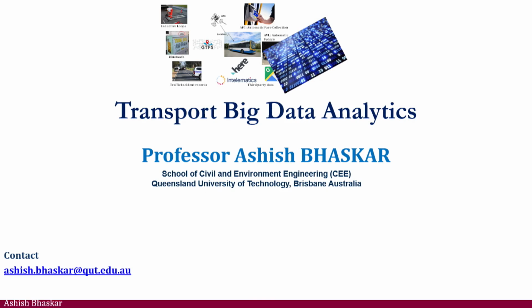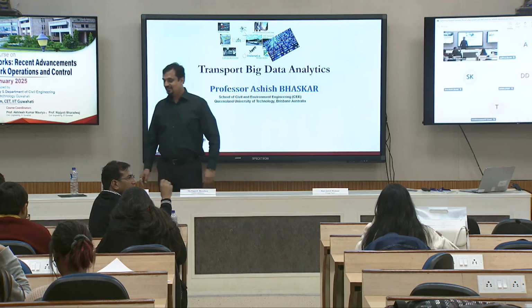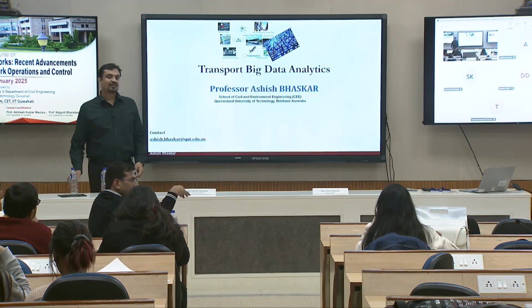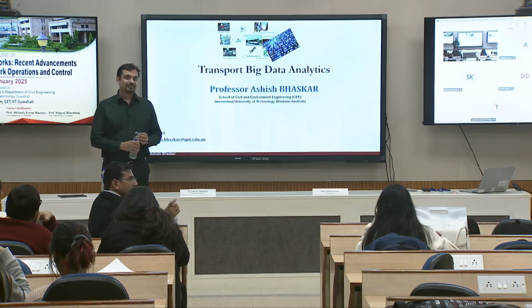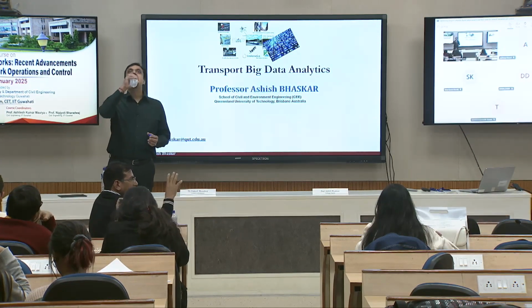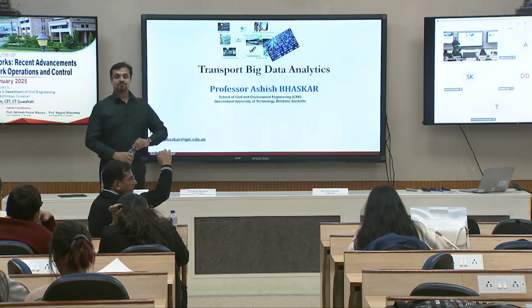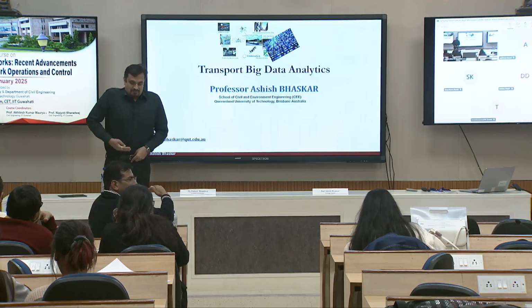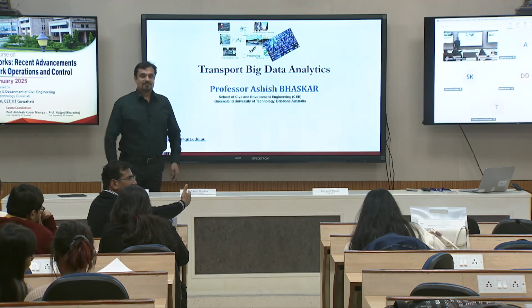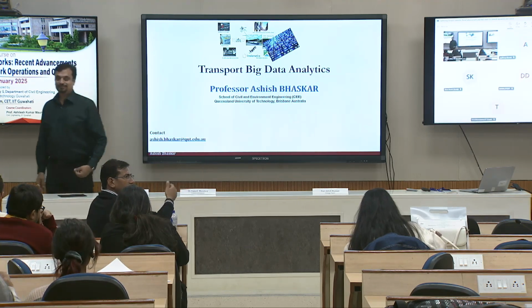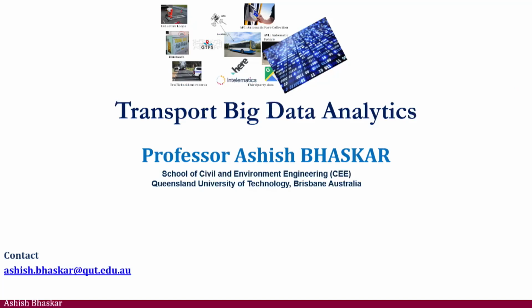You can connect it with whatever he has discussed about the signal, where you are blocking for some time and opening for some time. For the time you are stopping and then activating, you are losing something. So basically, you can assume that that is a time where nobody is moving. So the capacity, like you said, is reduced. So that's like the existing 4-lane road with some capacity now, and if you put in a toll, the capacity is reduced.